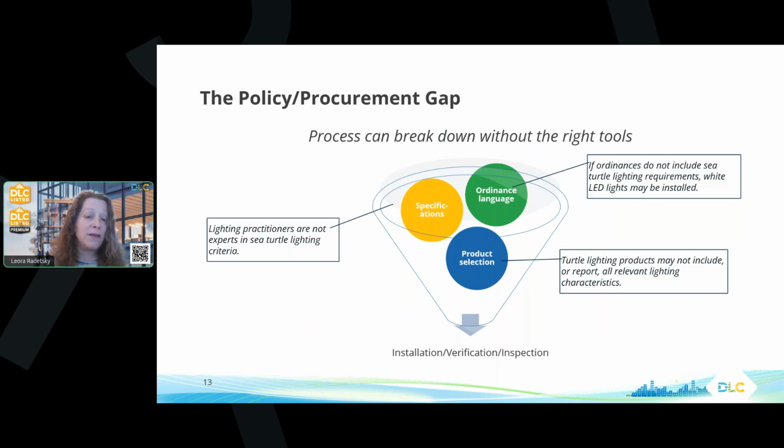Well, if an ordinance says use amber, for example, use amber LEDs, then procurement tends to buy amber products, and installation may proceed with standard output packages, standard luminous intensity distributions, and standard aiming and orientation practices that are perfectly acceptable for roadway and parking lot performance, but are not acceptable for a beach-adjacent sensitive habitat. And once the equipment is installed, plan reviewers and inspectors may have no clear basis to verify compliance beyond the label amber. And that's how we see well-intentioned retrofits yielding overlighting and spill onto beachsides.